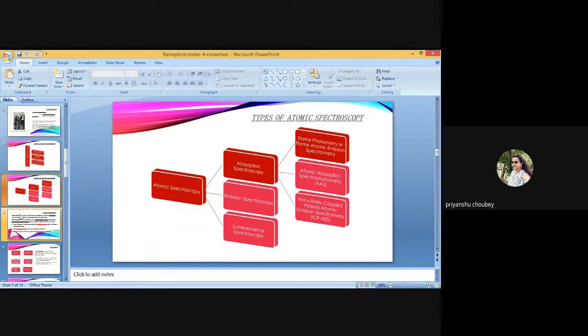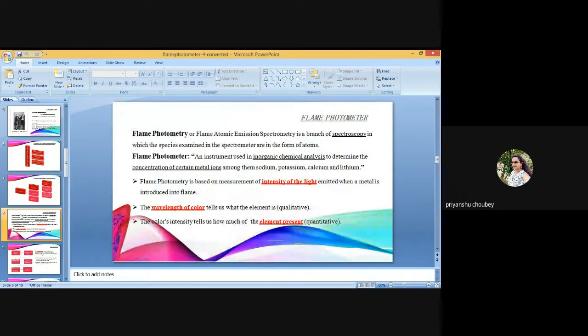An acetylene cylinder should not be used at a pressure lower than 500 kPa, 70 psi. Never operate the acetylene line above 100 kPa. At higher pressure, acetylene can spontaneously